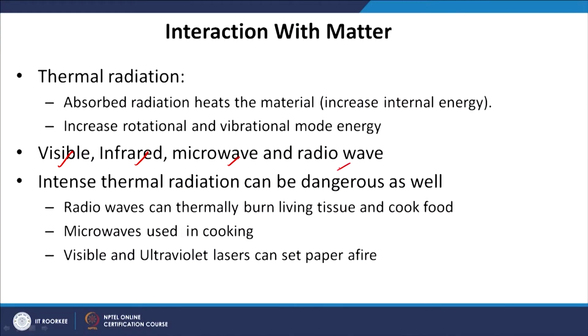On the other hand, there is something called thermal radiation, which is the most important from the heat transfer point of view, and in this category we have visible radiation, infrared, microwave and radio waves. So, all these radiations are long wavelength, greater than 0.1 micron. They are classified as thermal radiation because these radiations are responsible for transferring heat.